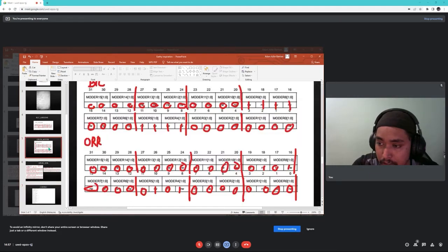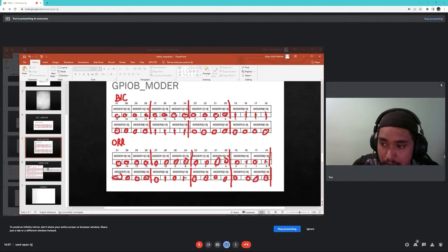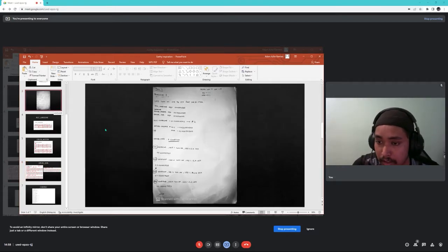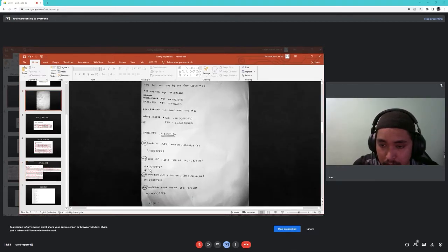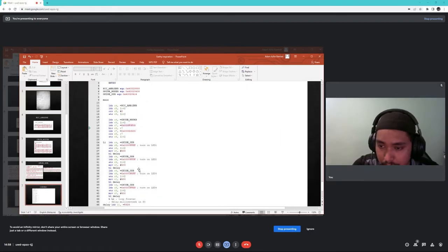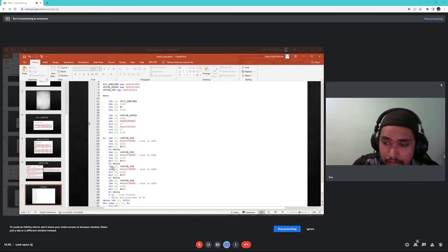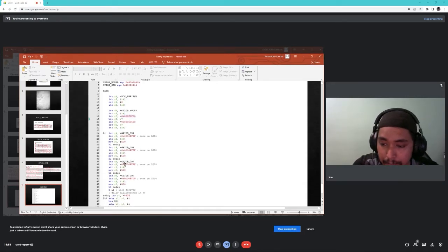FFDF here is the second condition we found just now, right here. 1101 is D, 1111 is F. And you can see here the second condition, 0000FFDF. We store memory R4 inside R5, and we have a 500 millisecond delay in R0.